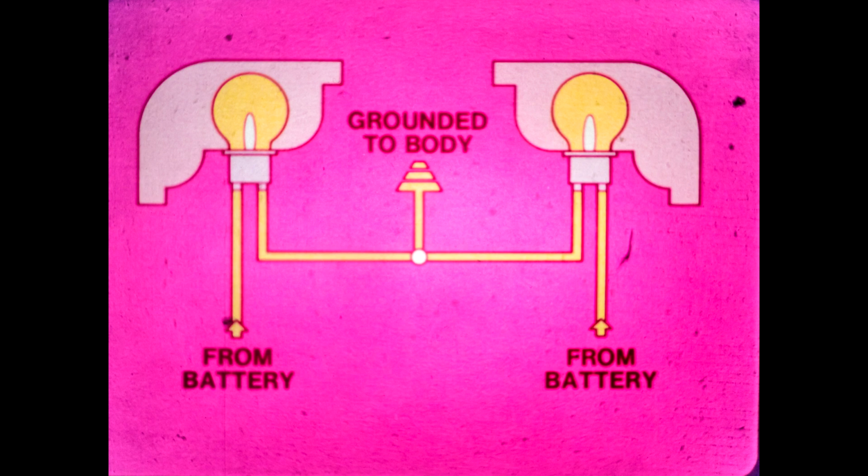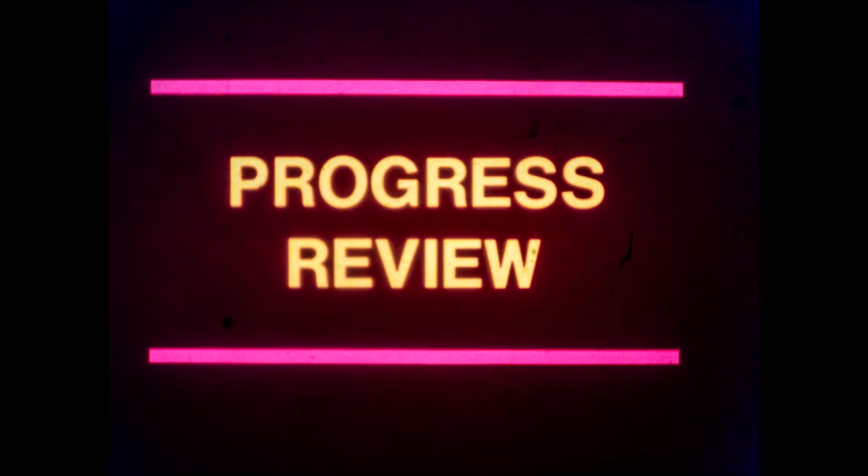In that case, a short, separate ground wire must be run from the working device to some point on the metal of the car. Next, let's review what we've learned so far. There's no need to write down any answers, since this review is for your information only, to give you an indication of your progress. Mentally answer the questions in the next few frames.